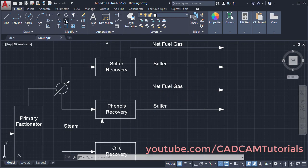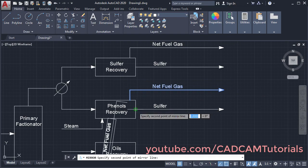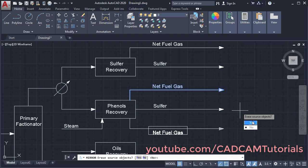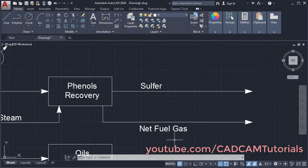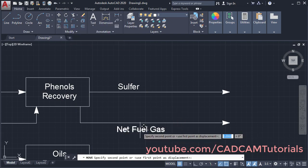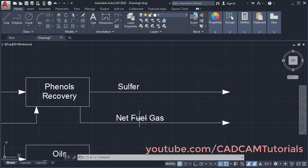Click on mirror, select this object, enter, then click on this endpoint. For the first point of the mirror line, take your cursor on the right side, ensure that your line is straight, click, then erase source objects, yes. Then move this to the upper side, click on move, select this object, enter, specify base point, take it above and click.